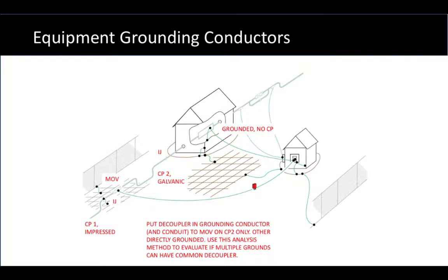But consider also that if conduit is in contact with the pipeline, it is part of the cathodic protection system up to the point of decoupling. The closer you locate a decoupler out near the pipeline, the less of that conduit run is part of the CP system, and therefore it's harder for an electrician to go and bypass it later in the future if they were to hang a clamp off of the conduit or do something with that conduit. Therefore, generally, a more foolproof system is where the decoupling points are closer towards the pipeline.